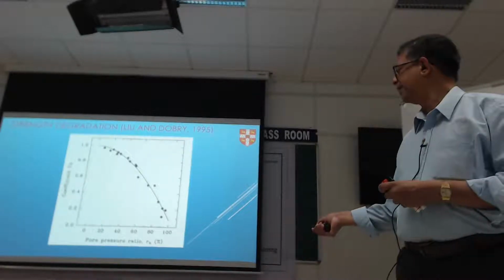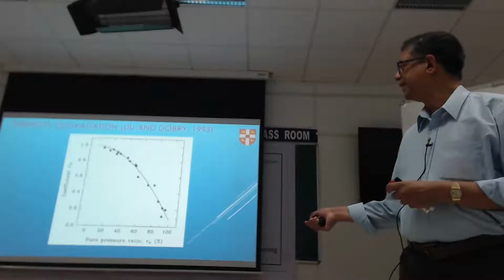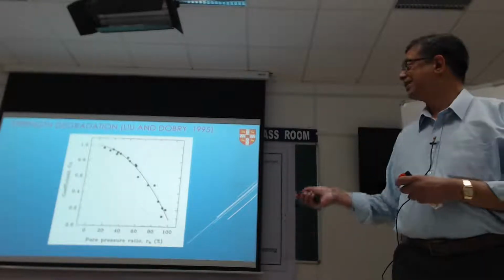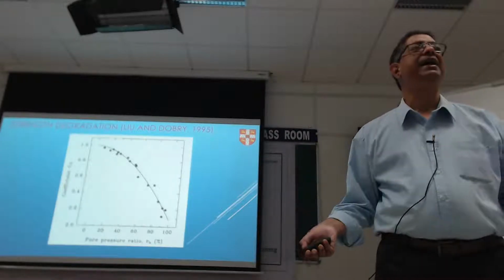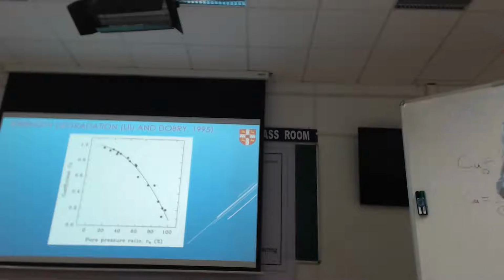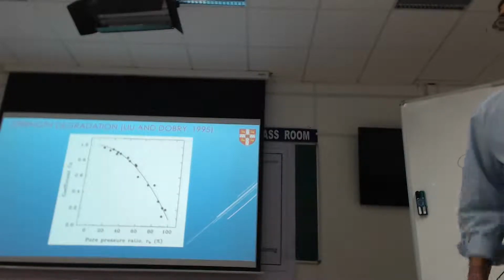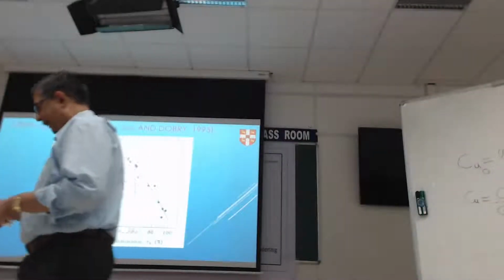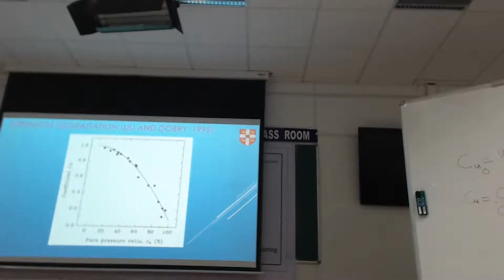So I go up here, say at 80%, I'll get a 70% drop off in my initial strength. So if I know that, then I can use that to see how much more my soil will move and how much more it will be acting on the pile. So this is another way of doing it. Again, this is based on experiment, so we've got to take it seriously.